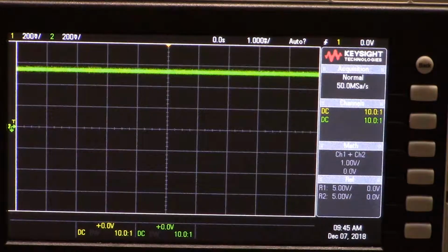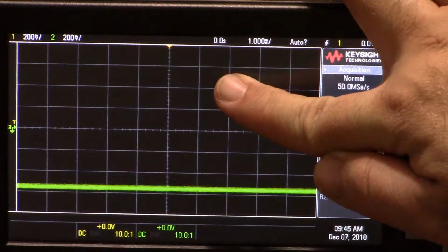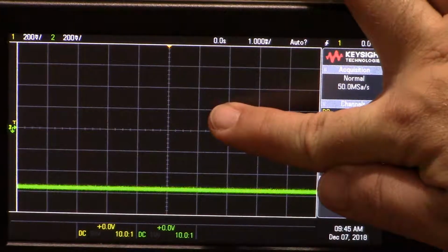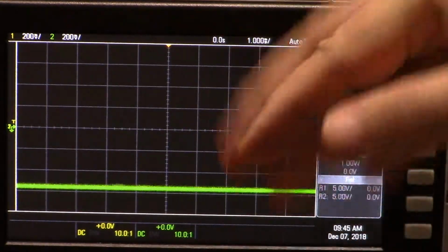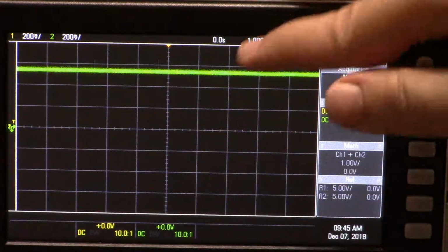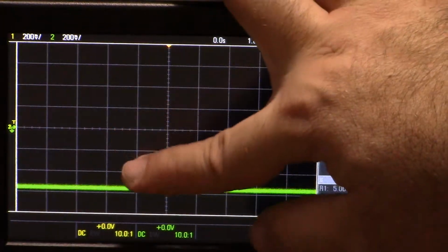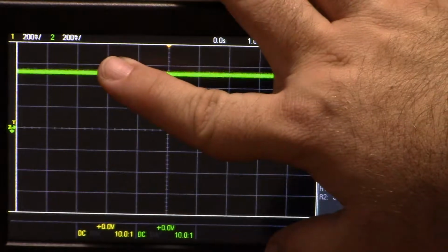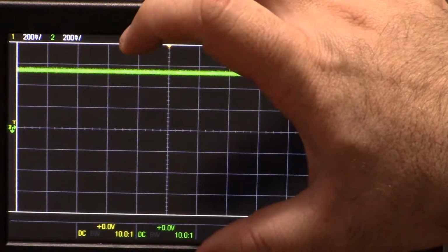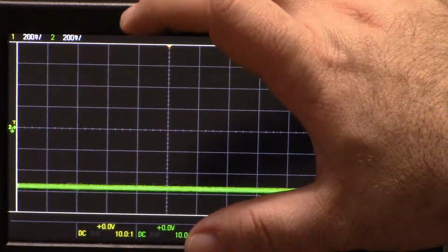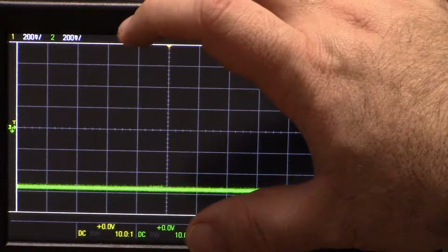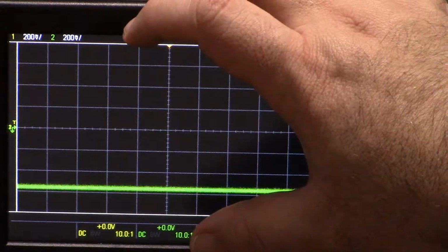Now, why did I do this? Because I want to actually measure the current. Because it's not enough to say, oh, we're getting a voltage signal out of this. Well, no kidding. We knew we would have that. Right now, we've verified the range of voltage. That's useful. So we can say that, maybe 1.2 volts. So let's just say 2 volts. Let's expect we're going to get no more than 2 volts and probably less, but we'll pick 2 volts as a safety that we need to handle.